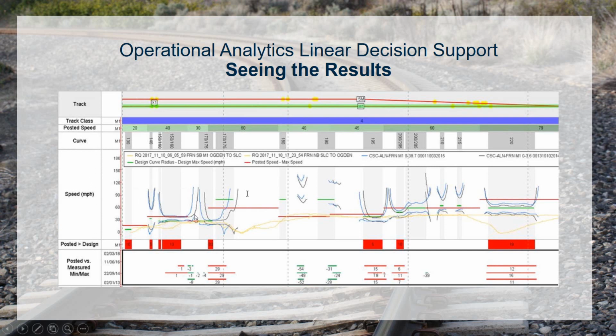The parabolas that you are seeing are a calculation of the max speed based on the radius of the curve, the superelevation, and taking into consideration the max allowable cant deficiency. This allows you to know exactly how fast you can travel through a curve. Below these parabolas is the equilibrium speed calculation, which is calculated to determine the minimum speed required through a curve.